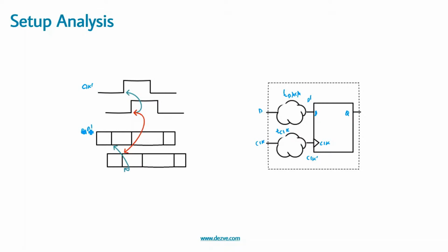So earlier the relationship of setup and hold was here. So this is still the setup and hold relationship with respect to this D prime and clock prime, correct? What I mean to say is, for the flop, this is the setup time, but the actual D prime and clock prime would be skewed by this much amount, correct?